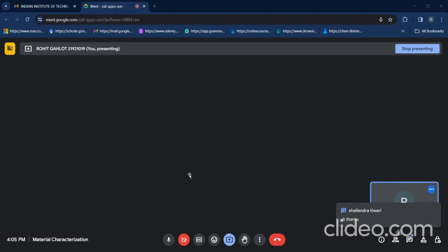And further, in the SE and BSE, there was one major difference in the detectors also. In case of the SE, if the collector voltage is more than positive 300 volt, then it will allow for both SEs and BSEs. For minus 100 volt, only BSEs will pass through. So this was one of the differences between your detectors for the SE and BSE.